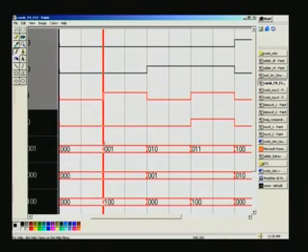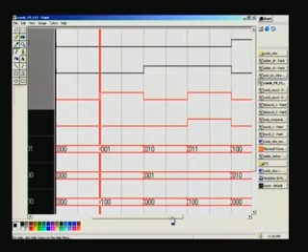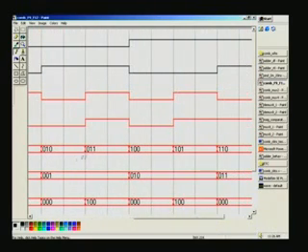And again the input is now in this case 0 0 1, and if you right shift here, what will happen? This 1 gets dropped, and 0 fills the MSB. So you continue to have only three zeros. That's why it is all the same. Now you see the difference. 0 1 0, if you right shift by 1 bit, this 0 will get dropped. So a 0 will get filled on the MSB. So what you get is 0 0 1. That's what you have here. And you can straight away explain in the same manner all this. So you can just see here.